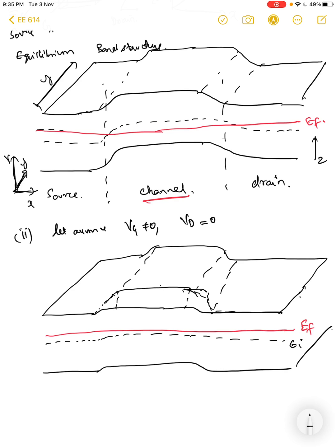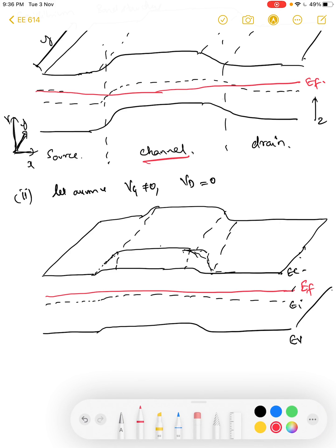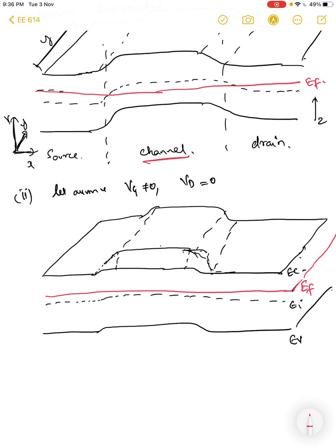Now let us consider what happens. So the EV, EC, I suppose now this is clear, right? You have to remember that the Fermi level goes the same way everywhere. But in the bulk of the semiconductor, the conduction band is still far away from the interface, and hence these regions still remain p.